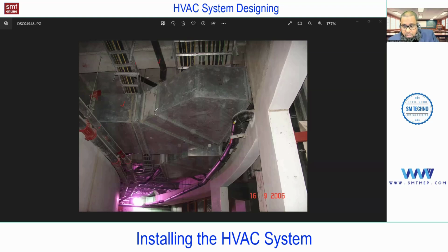So remember the height of the duct. If I use the term height, it is related to rectangular, including square. There is no question of height for round and oval; for that we have diameter. So forget about round and oval. For rectangular or square, the height of the duct will be decided as per the clearance available, considering the clearance required by the other services. This is one reference. But again, this is not that easy, and you cannot take a quick decision. You need some experience to judge, because in the height of the duct also we have some limitation.